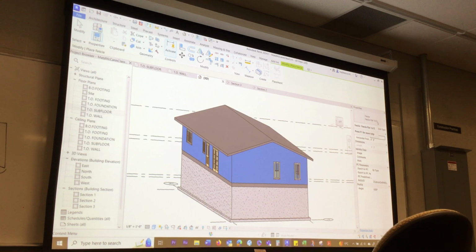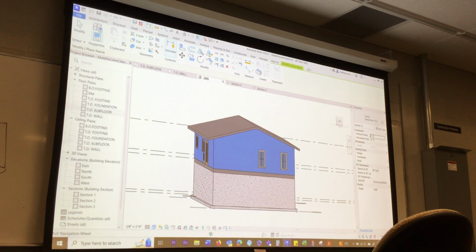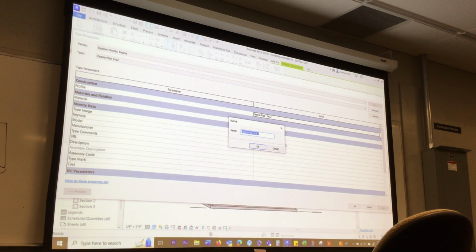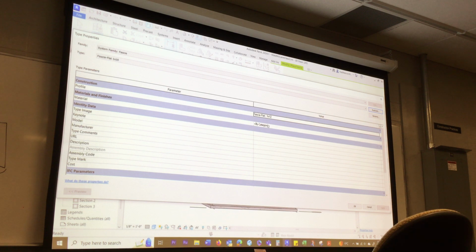How big do we want our fascia? 8 or 10 inches at least. I like big, thick, chunky fascia. But if you put too thick a fascia on, you won't see out the windows very well. Let's put 10 inch on, let's be brave. Do they have a 10? No, it only comes in one size, so we need to edit, duplicate, fascia 1 by 10. So this is like 1 inch thick, like a Louisiana Pacific Smart Start batten type stuff. It's pre-primed, really nice stuff usually. It's a decent product. So okay to that. And where do we change its darn size?